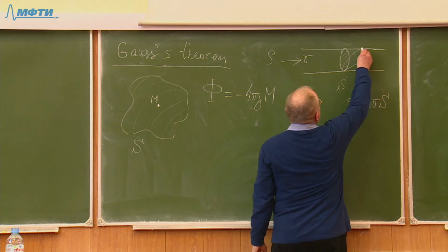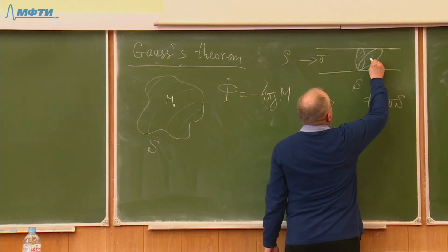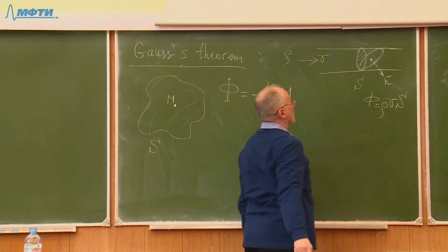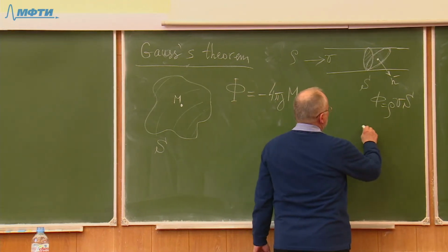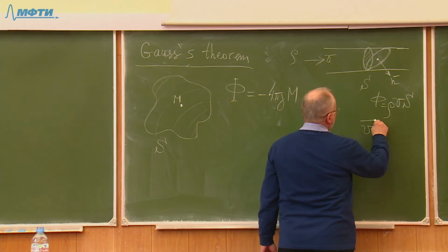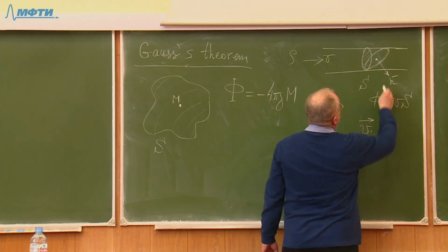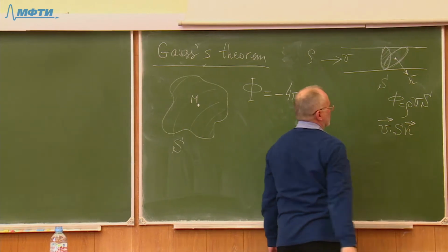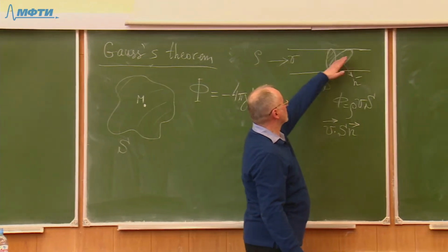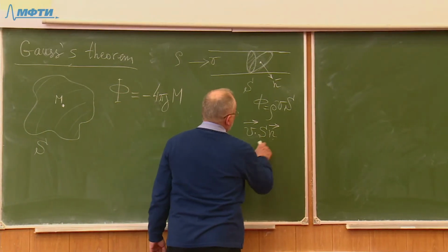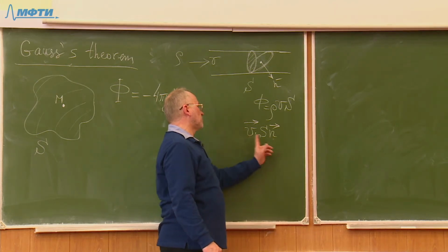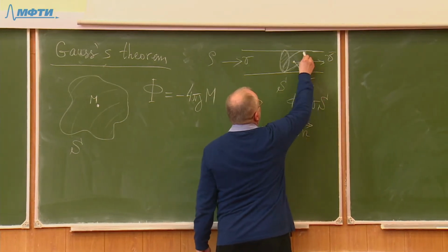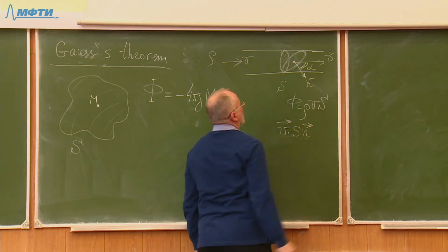It's easy to see that if we introduce a perpendicular vector, a unit vector n, which is perpendicular to this surface area, and if we introduce such a quantity as scalar product of vector velocity by the area and unit vector perpendicular to the area of some cross section, then because the scalar product will include a cosine of vector between the velocity and unit vector which is perpendicular, it will include the cosine alpha.